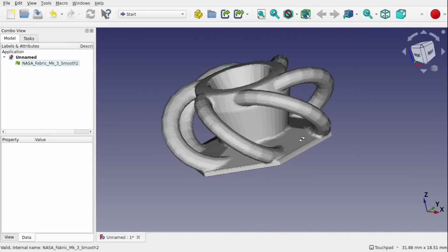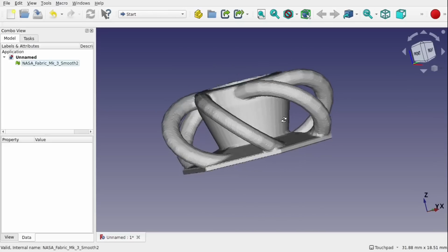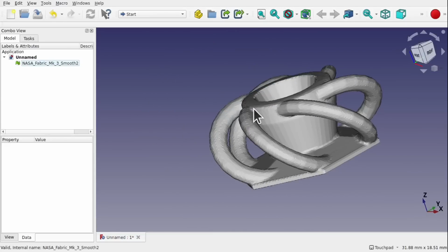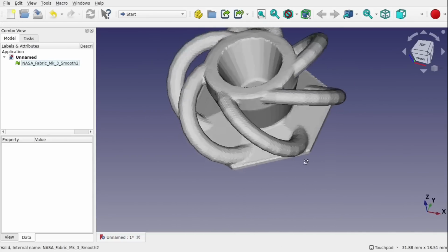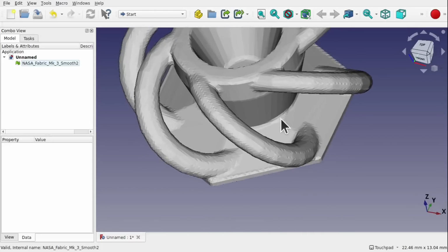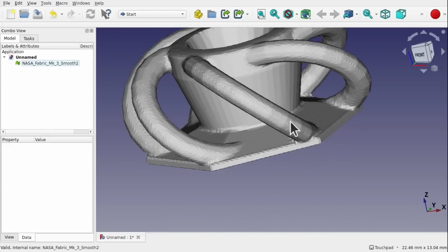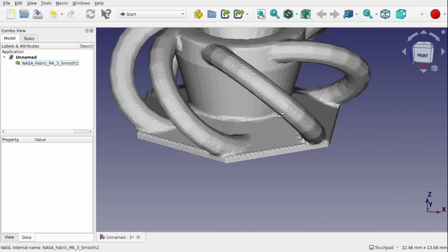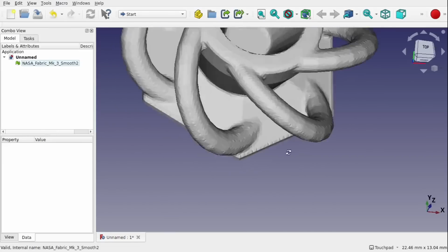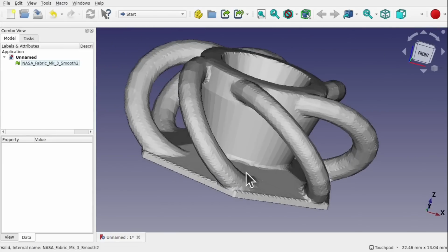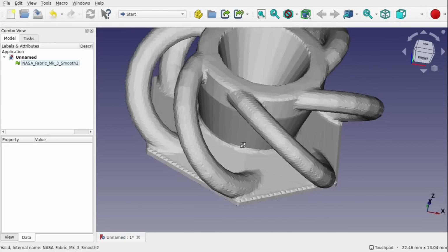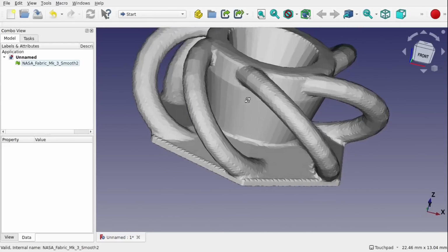So we're looking for a workflow that will work with this. I'm going to go down the part design workflow for the lofting, and the problem is these ones, because they're going to be quite awkward to do. Now looking at this, we have got this line that follows this loft, and on that line is the start of this arm. If we come down and measure up, looking here, well, when I say measure up, we line up, we can see that this line here more or less intersects the center of this arm.